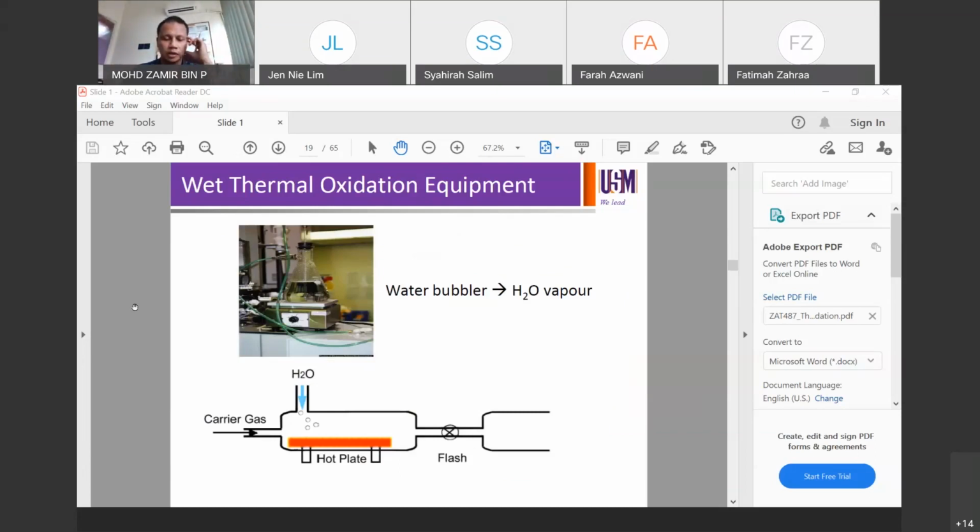So the configuration of the furnace is illustrated below there. You have a carrier gas, then you have water vapor after it has gone through the water bubbler. So then the water vapor comes into the tube. In this case, it is a horizontal tube, and then you have your wafers on quartz boat, and the tube is encapsulated by hot wires in order to ramp the temperature to your desired temperature to do oxidation. Okay, that's how it works.